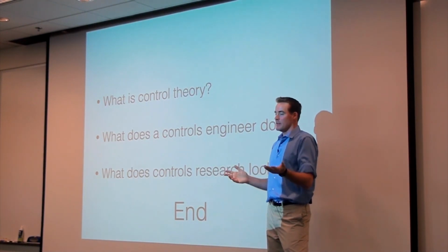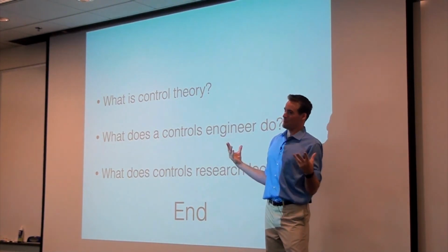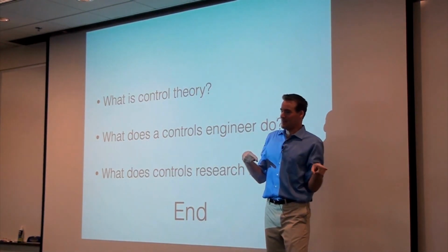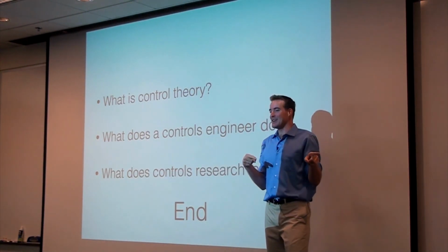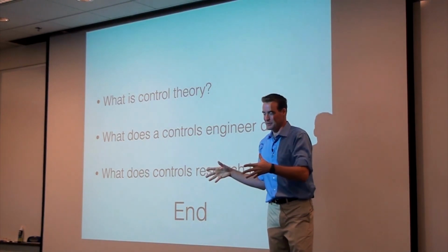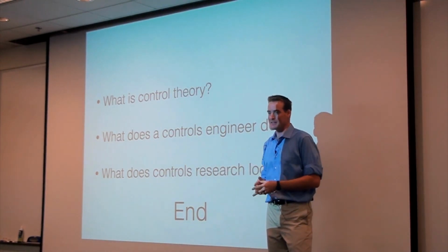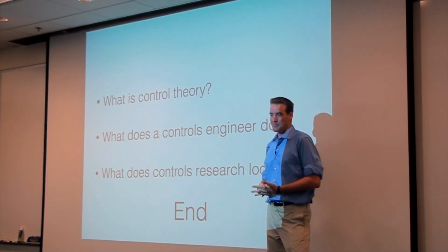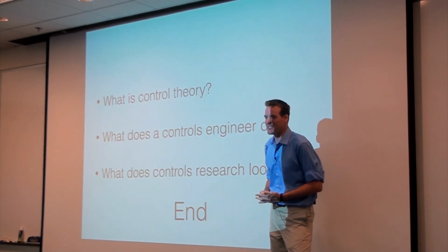If you're not measuring the derivatives, you could just differentiate the things you are measuring, but that leads to much poorer performance than if you have an internal observer. You probably knew that though.